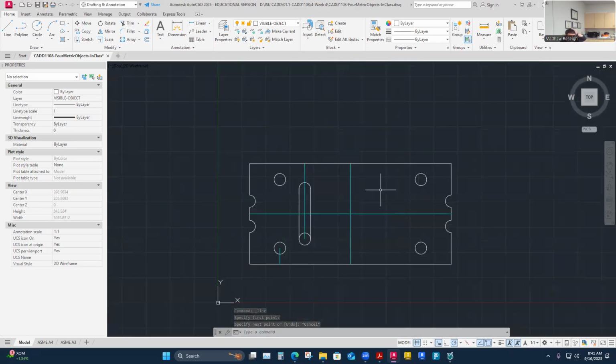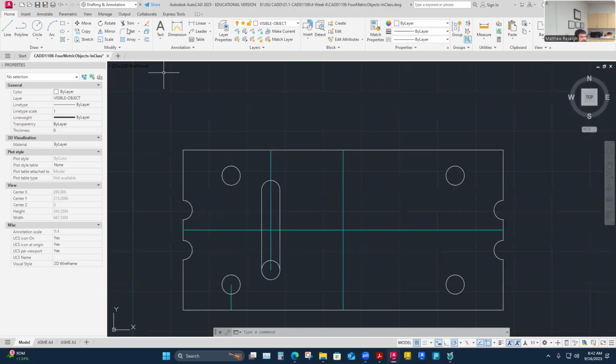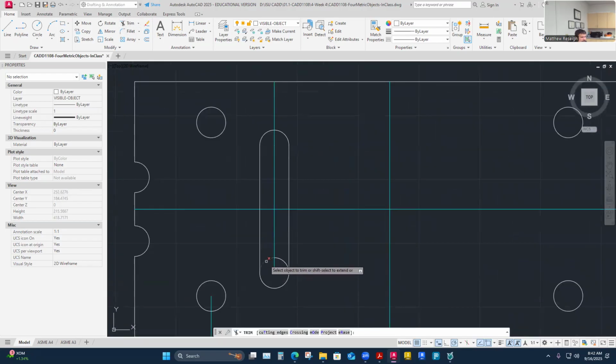Yeah. I don't think we've used the quadrant snap too much, but in this alignment, it doesn't always work. Sometimes I need the tangent line function to actually touch. When you do your rocker arm number one drawing yourself, quadrant would not be the correct way. You'll see when you draw that you do a similar thing where you're connecting a straight line across two circles, and in that case, you have to use the tangent. So it depends on the geometry. Really, for circles to use quadrant as a point of tangency, they've got to be in the right alignment, usually vertically or horizontally. So there it is.